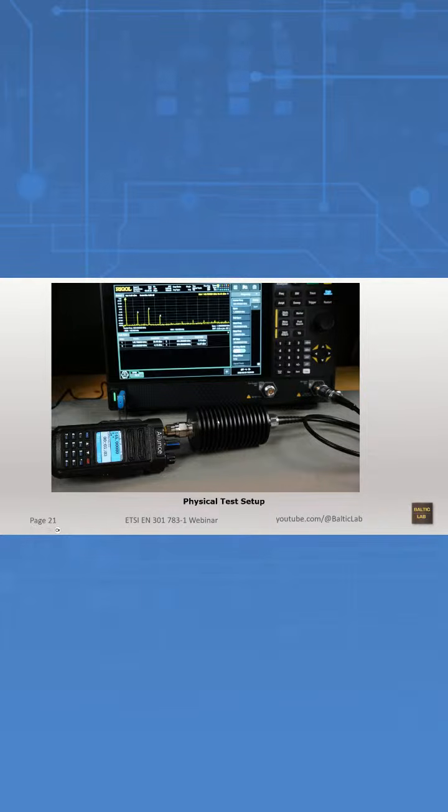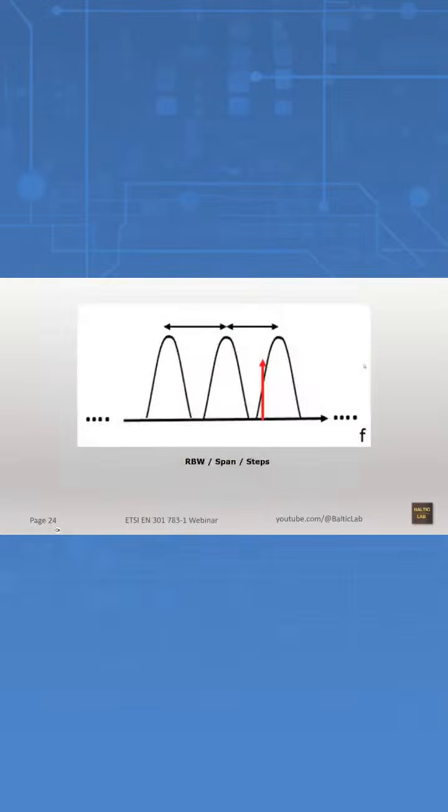We go back. I have 30 decibels here, and I have 20 decibels here. That's the sum of both attenuators. Problem with that is, as we've seen earlier, it's frequency dependent. The attenuation of the cable is also frequency dependent, so I can't just say it's 50 decibels. It changes over frequency.